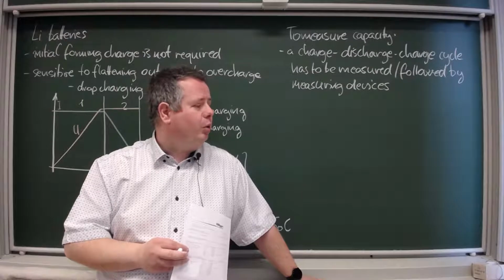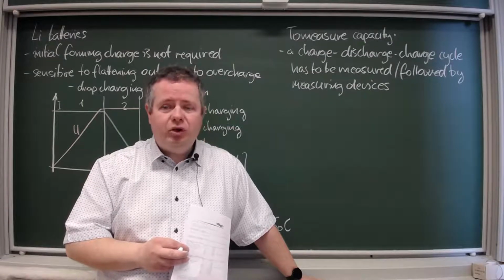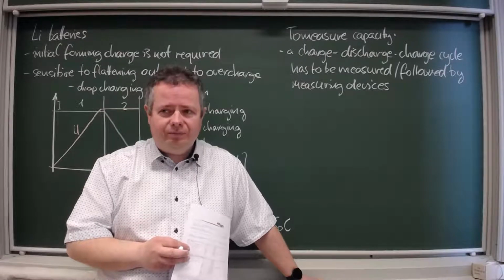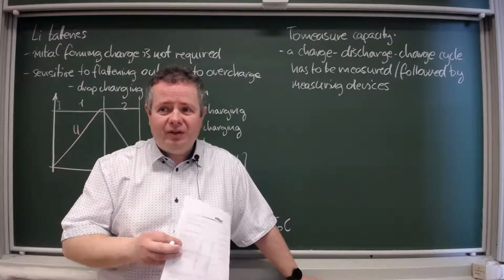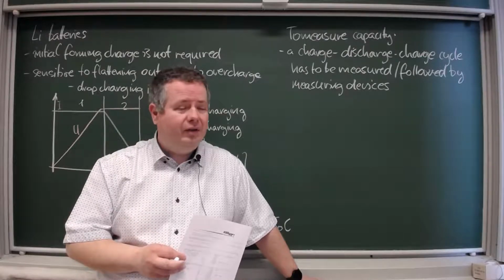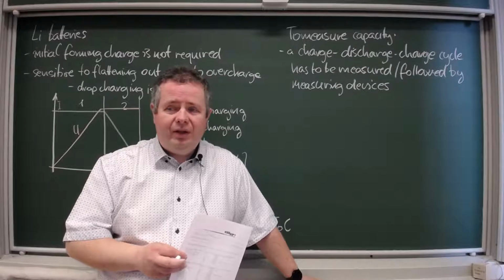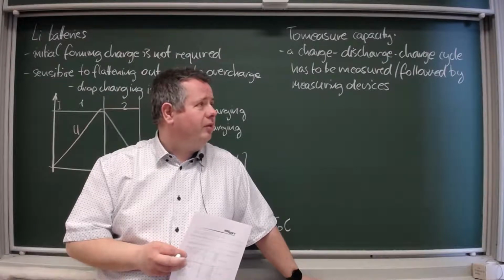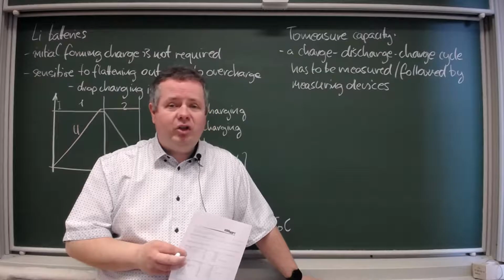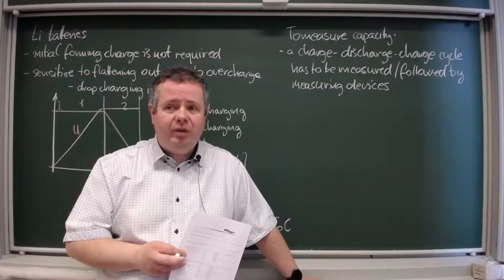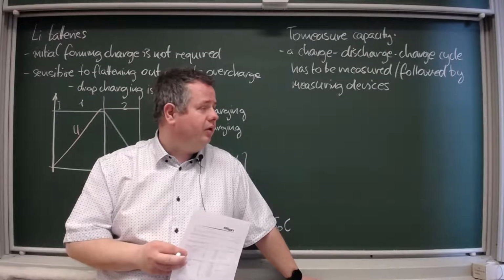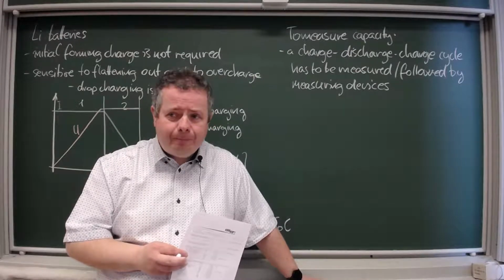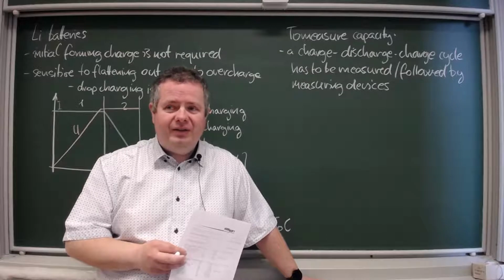I don't know how it happens with the Tesla, but I'm afraid there's also some method like this for estimating. And once the capacity of the battery is measured, usually the autonomy of the car is fine-tuned, so it's set upon what is in reality with the battery. At the Teslas, they are doing that by software, and in the older Japanese electric cars, Mitsubishi iMiEV or Citroën C-Zero, Peugeot iOn, it's done like that.